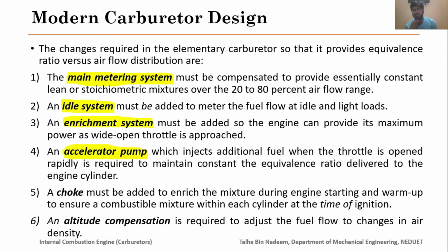The only difference is that the accelerator pump operates when you have suddenly increased the load, or suddenly pressed the accelerator pedal of your car, because in that case the throttle valve has suddenly opened and a large amount of air is coming through the venturi section, but due to the inertial effects the fuel is not increased that much, and the air is not taking out that much fuel.